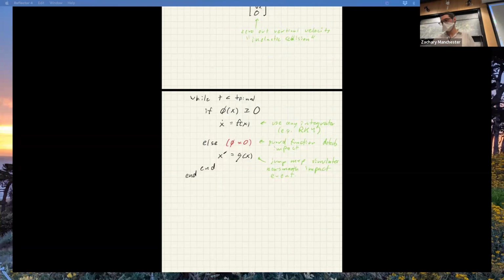For example, in this case it's fine to be frictionless, but if you have friction, our jump map just says preserve x velocity, whereas if we have friction, we have to be changing x velocity. Yep. So basically, this story gets a lot more complicated in general. In this particular setting, sliding versus sticking are two separate modes. So yeah, Coulomb friction is also discontinuous, right? You'll have a bunch of modes and you'll have jump maps between every pair of modes.